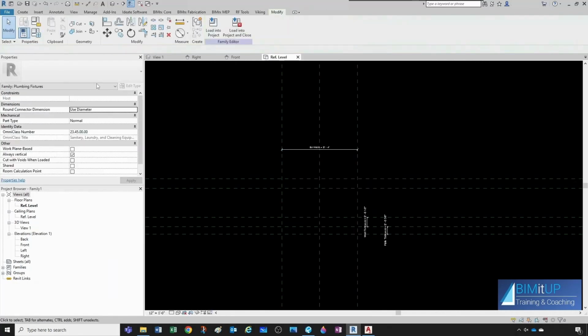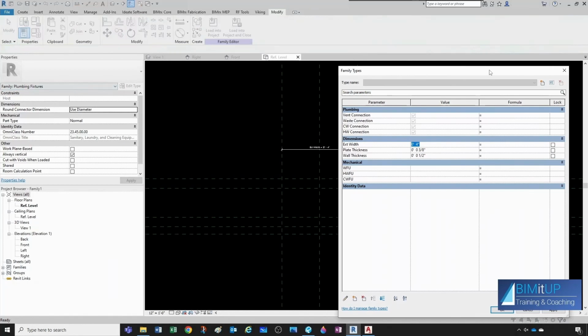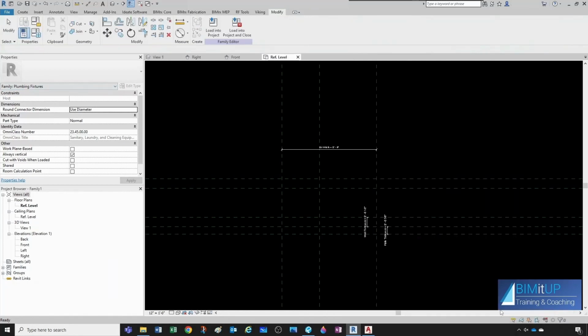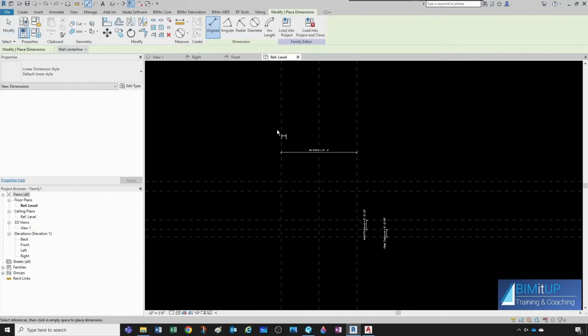Okay, and now I'm gonna give it the right value, which was 5 inches. And I actually like doing this because then I see how things flex in real time. Oh, I made a mistake here, so I'm gonna do undo. What did I miss? My equal constraint. So that's important. So let's do that from here to here to here.